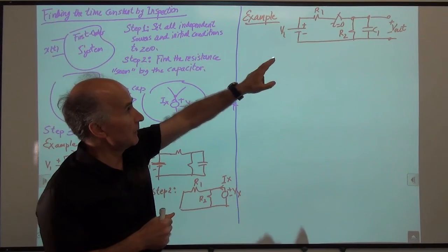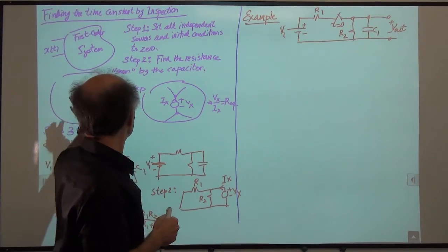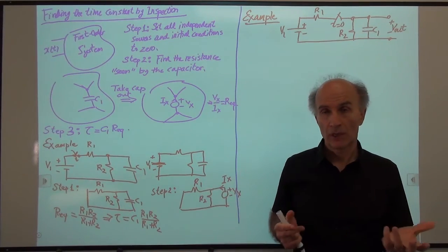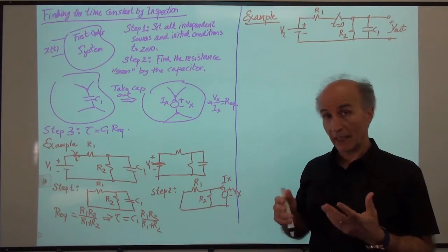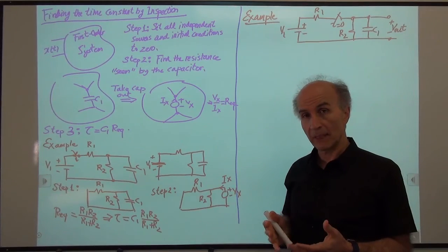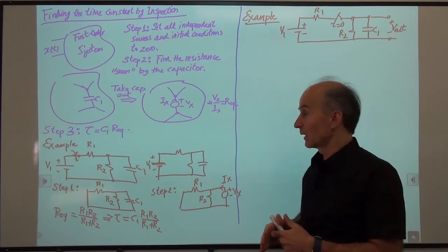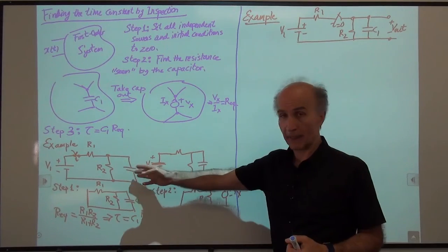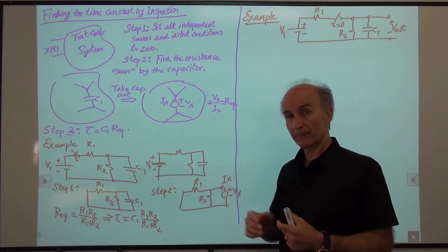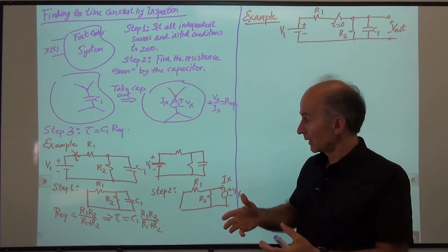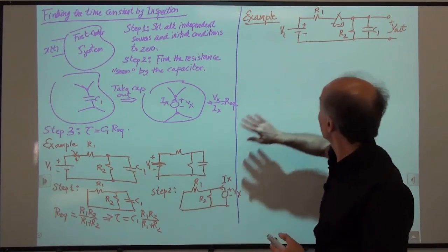Is there any difference between that circuit and the circuit here? No, not really. If we look at the output V out, we see that V out is 0 before time 0 because we are given that the initial voltage on the capacitor is 0. And then after time 0, when the switch begins to conduct, there is no distinction between this circuit and that circuit, right?